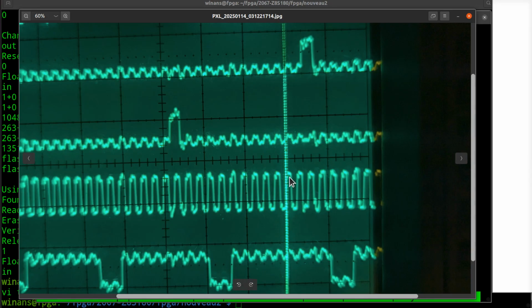Here's T1, here's T2, and you can see that this thing goes true on the leading edge of T2. Is that? No, it's on the falling edge of T2 because this darn thing's crooked. And then it goes back down on the falling edge of the wait state here. Here's T3, and you can see down here, there's the next instruction.